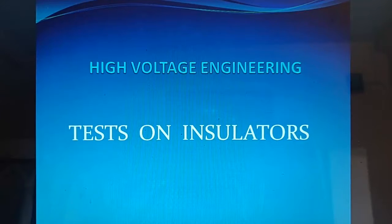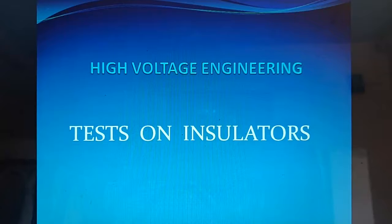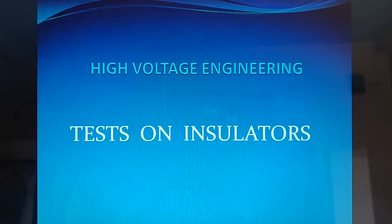The first is cracking of the insulator. The porcelain insulator mainly consists of three different materials: the main porcelain body, the steel fitting arrangement, and cement to fit the steel part with the porcelain. Due to changing climate conditions, these different materials of the insulator expand, and this unequal expansion is the chief cause of cracking of insulators.